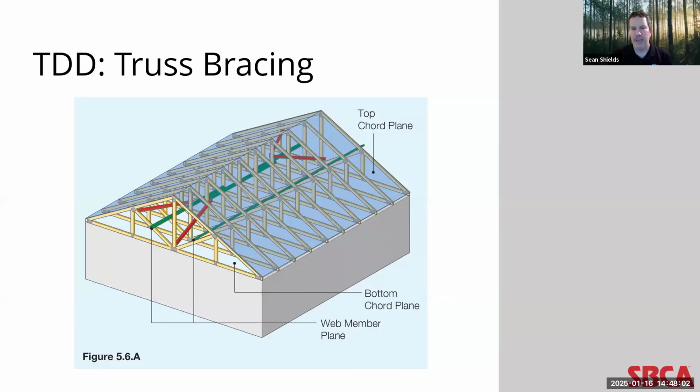Now, again, trusses are designed as essentially two-dimensional framing elements. Their ability to resist loads is maximized within the plane of the truss, from the top chords down through the bearing locations. Yet, each truss element works within a three-dimensional roof or floor system.